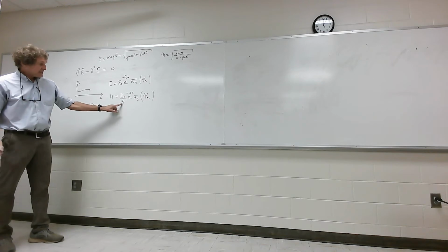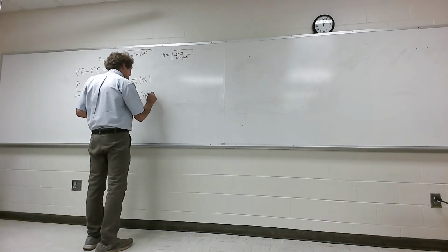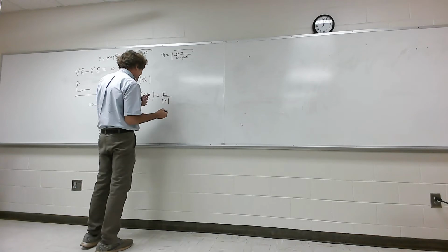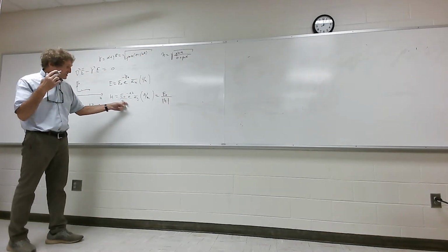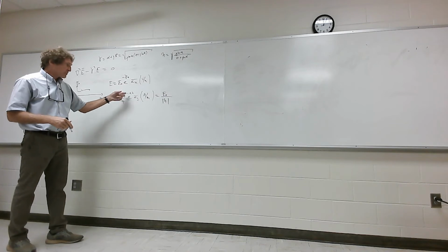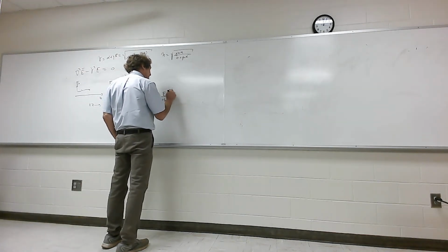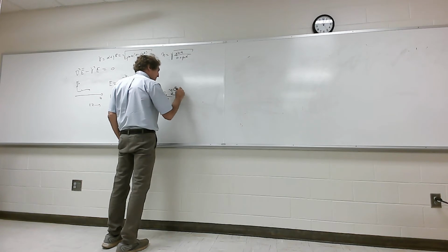That has a magnitude and a phase possible. So the normal way we talk about this is some E naught over the magnitude of eta, and then the phase angle here would be e to the plus j angle associated with eta, but when we take it upstairs, it becomes e to the minus j angle of eta, times e to the minus gamma z.